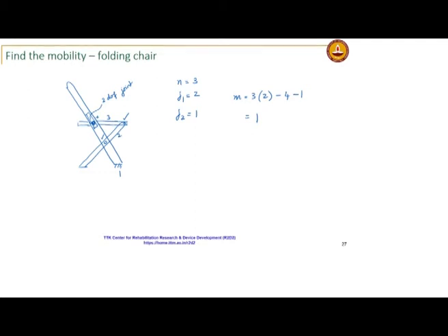For most planar linkages, the joints that you are going to encounter are your revolute pair, prismatic pair, rolling or a cam pair. Okay. Planar you can think of as prismatic plus rotation, like in your drafter, right there.